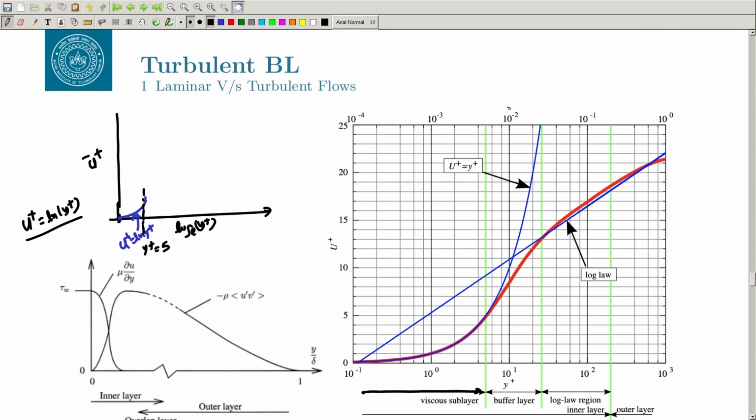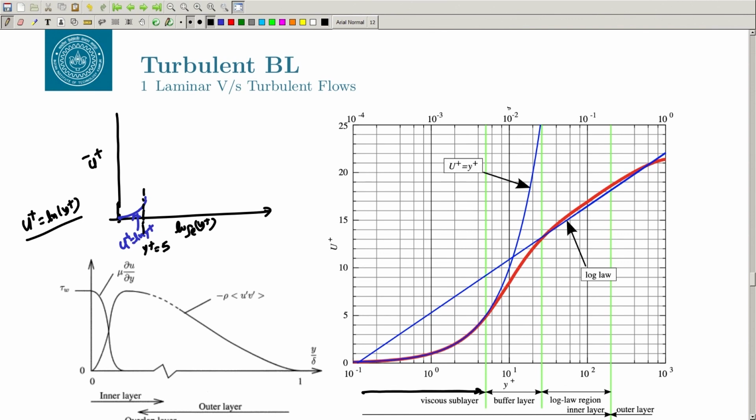Okay. So, let us say you are not using y plus less than 1 in your simulation, that means you are not resolving the viscous sublayer. Of course, there are some wall functions which can feed this function for you, and it allows you to use a higher value of y plus. But if you are solving to the wall, you must ensure that you are solving the viscous sublayer also. Then you must have at least 5 grid points to solve that layer. So, if y plus equal to 5, then you need y plus less than 1 to basically resolve the viscous sublayer properly, right. And then in between you have this buffer region where none of these laws are valid, okay.